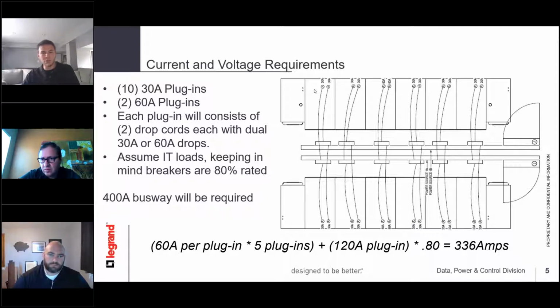As for the PPE, we do recommend wearing the minimum rating of PPE. It is minimal, but there are locations out there, which I've been involved with, actually manufacturing locations, where they've done arc flash studies on them, and they have found that these have a 0 arc flash rating. And that's all based on your facility, where the busway is located as opposed to people and whatnot. This was, I think, 10 or 15 feet up in the air, where they were able to put that rating on there after they found out that this is a safe system.